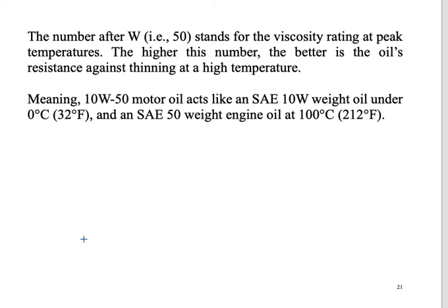The higher this number, the better the oil resists thinning at high temperature. Meaning 10W50 motor oil acts like an SAE 10W weight under 0 degrees Celsius, and as an SAE 50 weight engine oil at 100 degrees Celsius.